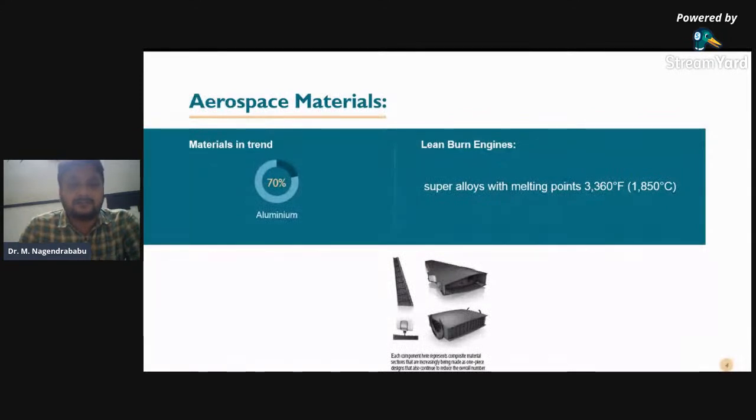Times have changed. A typical jet built today is as little as 20% pure aluminum. Most of the non-critical structural materials, paneling and aesthetic interiors, now consist of even lighter carbon fiber reinforced polymers, which we call CFRPs, and honeycomb materials. Meanwhile, the engine parts are critical components. There is a simultaneous push for lower weights and higher temperature resistance for better fuel efficiency, bringing new or previously impractical to machine metals into the aerospace material mix.